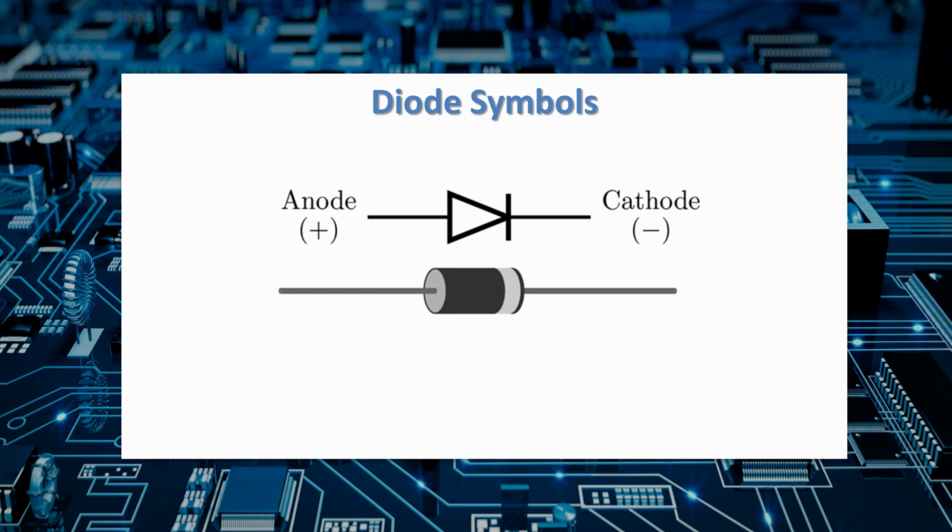Diodes normally only allow current to pass in one direction, from the anode to the cathode. Zener diodes, however, are designed to allow current to pass in both directions, but in the reverse direction, they limit that current flow to a specific voltage. Therefore, Zener diodes are often used in voltage regulator circuits.